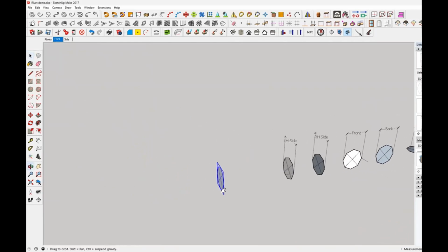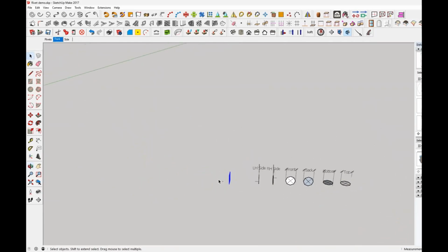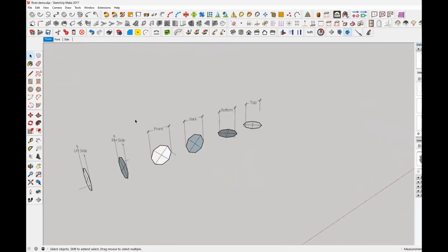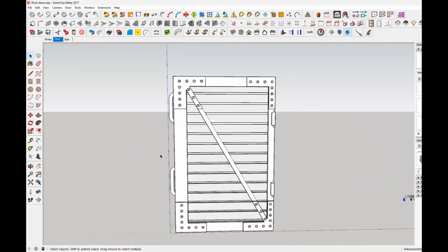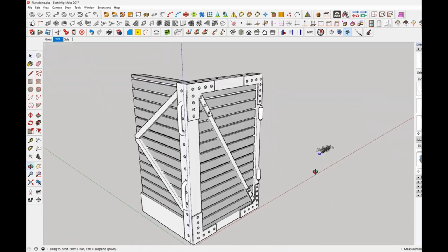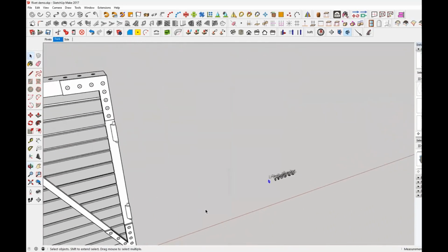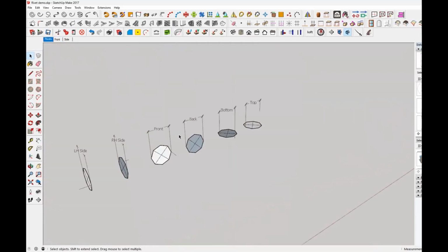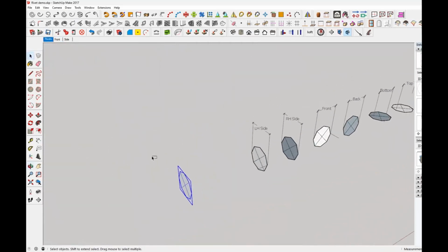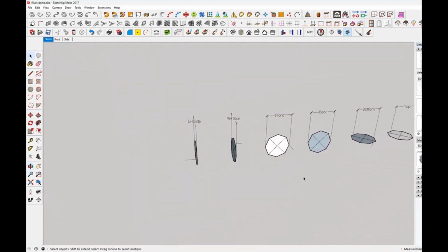So I know now if I want to put a rivet, let's go to rivet, we'll go to front. If I want to put a rivet on the left hand side, I can pick that one, do a control, drop it on and run it down there, and the faces are all facing the right way. So if I go back to the rivets, what I done was, I checked 6 sides sitting there, top, bottom, left, right, front, back.